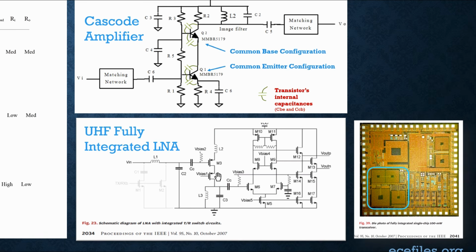Now, it gets tricky. Number one, these are MOSFETs, but I've drawn them in such a way that hopefully they remind us of BJTs. And they really work pretty much to a first order like BJTs, so don't worry about the MOSFETness of them. The other thing is these are P channels, so they're like PNP transistors instead of NPN. So this configuration is flipped vertically relative to this one. But the signal is coming in on the gate here, which is like the base here. And then there is the cascode transistor. And then here is that tuned circuit, which in the top diagram is up here.